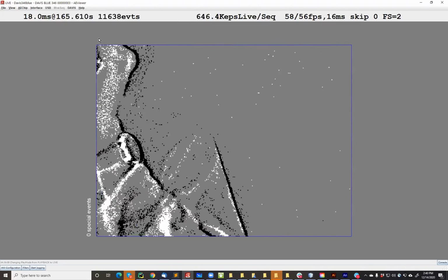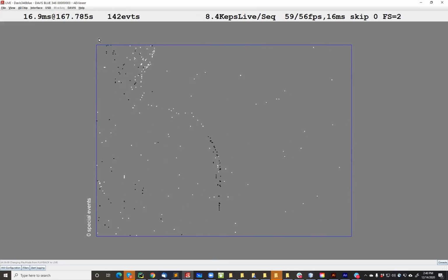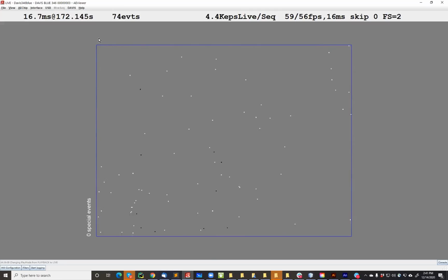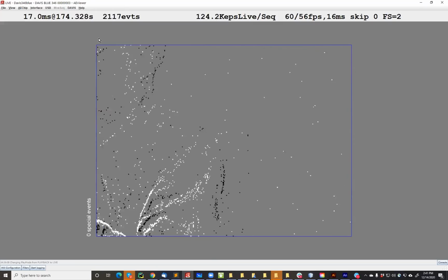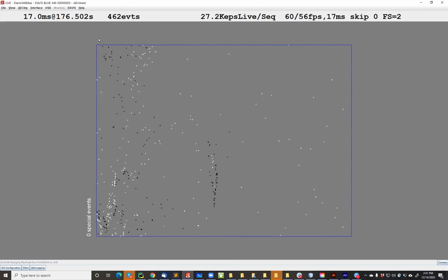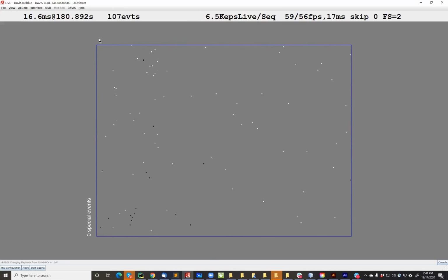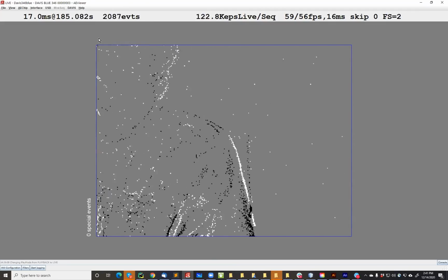That's what we did here on the retina. We put one of these IMUs on the back of the chip. Now, what is that good for? What can you do with that? Once you have this vestibular system built together with the camera, what would you do with that? Well, you could electronically stabilize the output, de-rotate the picture. So let me show you.